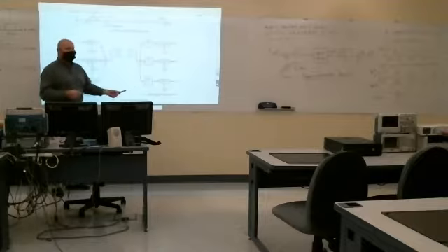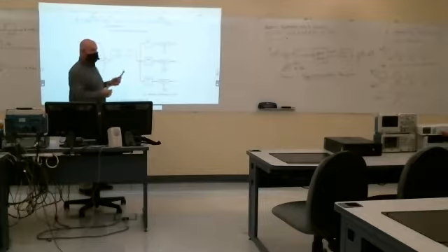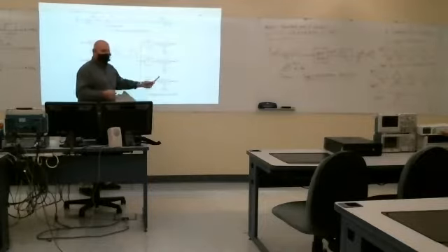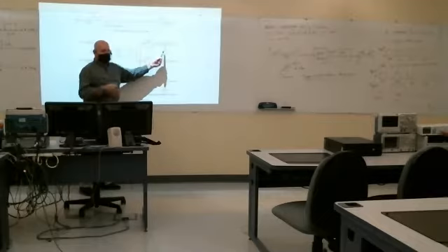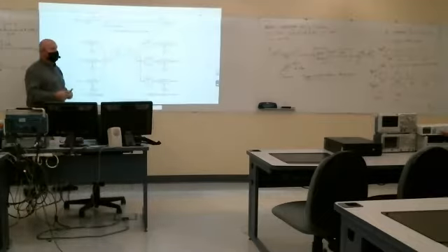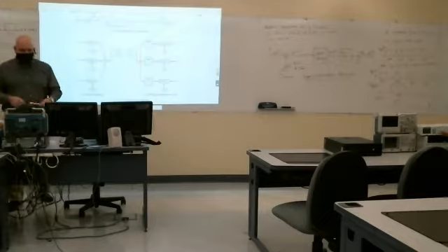At a receiver then, we can filter out each one of them. You could use bandpass filters like this or actually use the super heterodyne technique. Bandpass filter to separate out all the different voice channels. Then we have to demodulate by multiplying again by the same frequency to recover X1 of T. But it really is that simple.